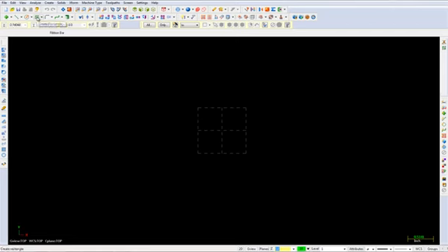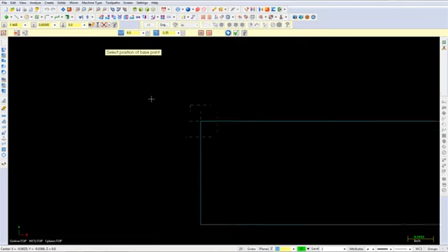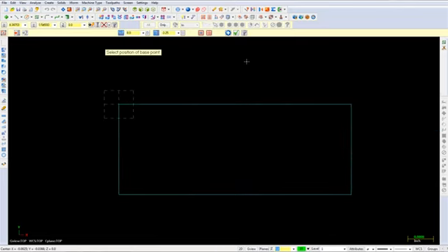To begin, choose the Create Rectangle command. Change the width to 8 and the height to -3.25 inches. Ensure that Anchor to Center and Create Surface are not enabled. Then select the origin. Zoom out to see the rectangle.